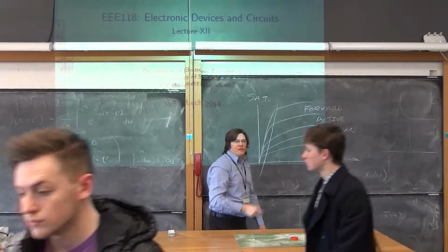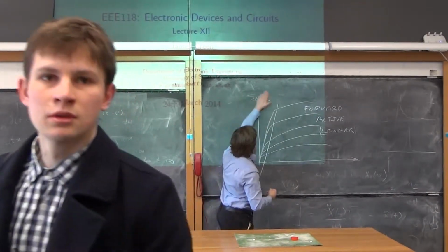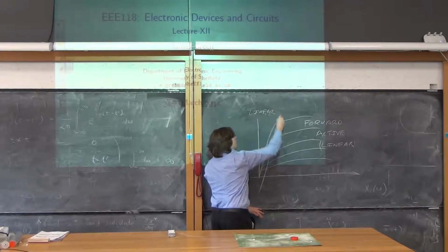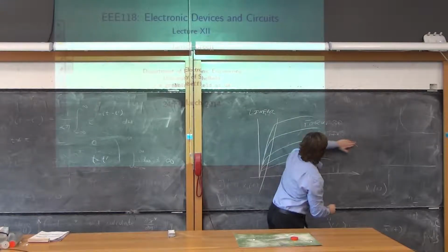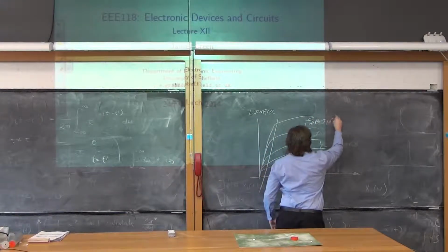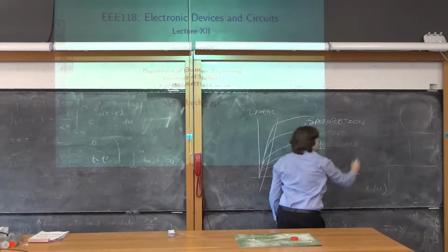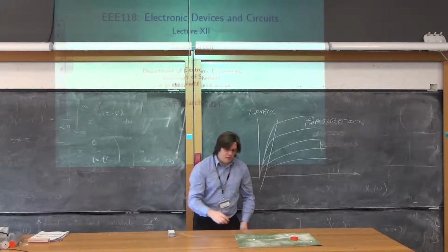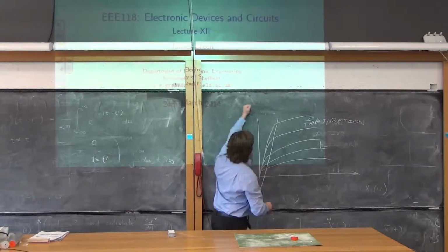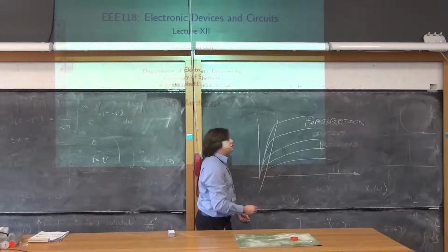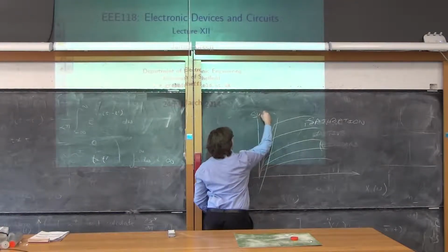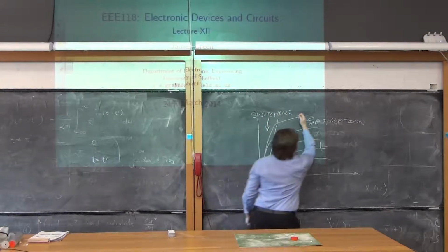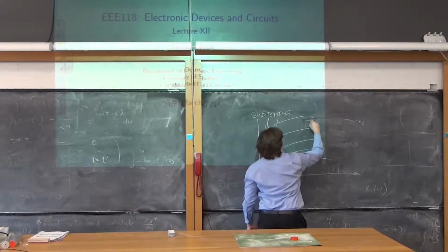But if it was a field effect transistor, I would have said that this was linear and this was called saturation, which is a thoroughly confusing situation to be in. So I'm more than happy for you to abandon that and think about a bipolar transistor and a field effect transistor in which this region is called switching and this region is called amplifying.